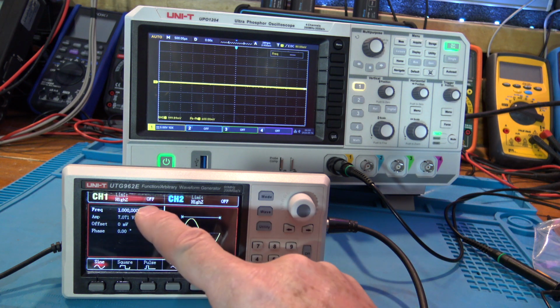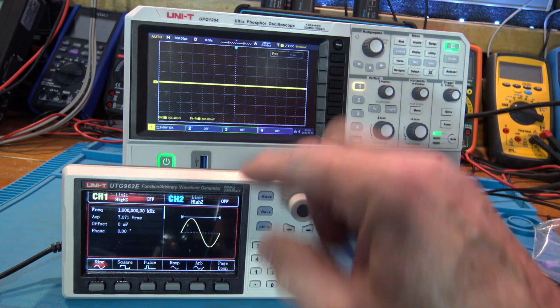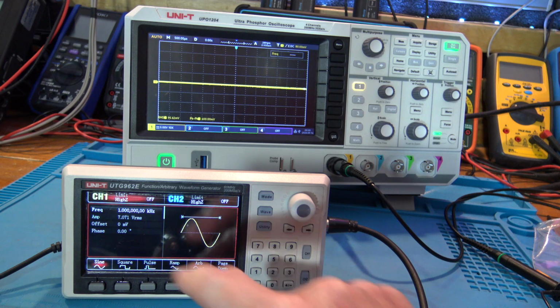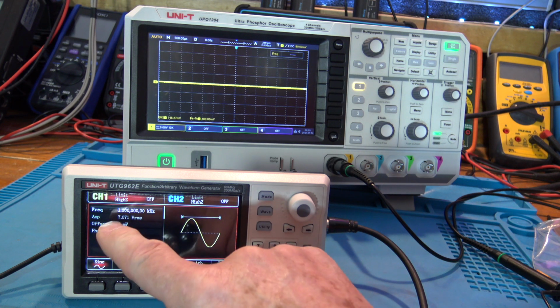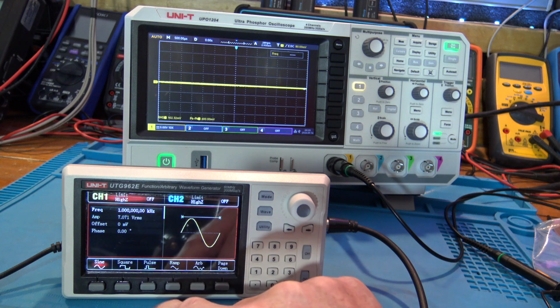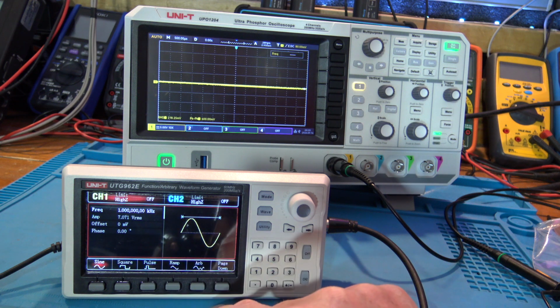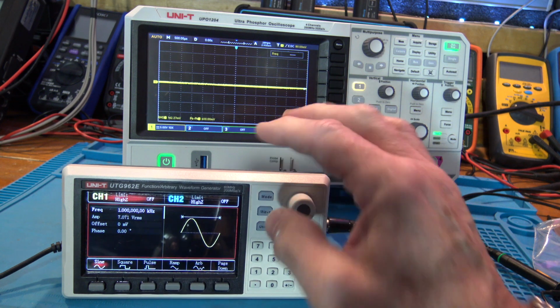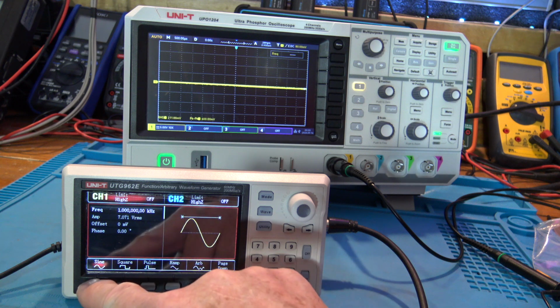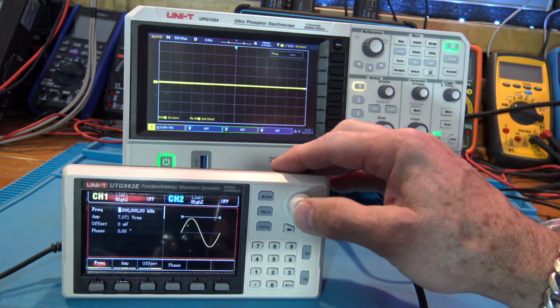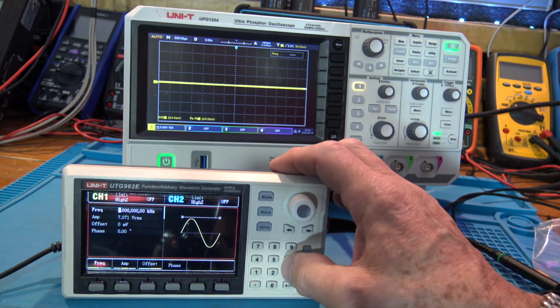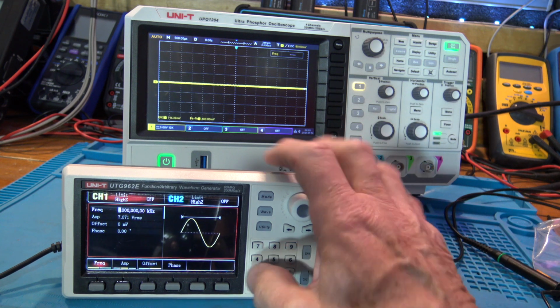It says high Z off and high Z off, okay? Here, let's just talk about that for a moment. Well, actually, you know what? This thing looks like it's set for frequency. This one's showing that it's sine wave. All right, so if I go to wave, it shows me the different waveforms, and I can say, okay, yeah, I want to be sine wave. Okay, so I just push this in, click on that, and then I can say, oh, what's the frequency?